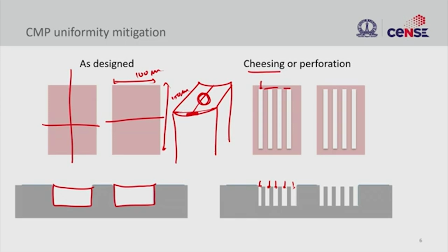So when you do this, your filling is going to be uniform. So you will not have any dishing in this case, right? You can have very uniform filling, so that it becomes very reliable. And then you can also have a larger contact that allows you to make this further contacting or bumping, whatever you do, pretty easy. So this is only a concern at higher metallization levels, right? So not at